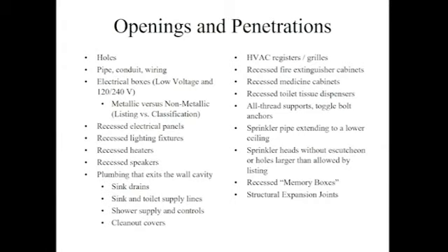Medicine cabinets, I can't say I've seen a rated medicine cabinet yet, so you need to be very careful about how that's detailed. Putting in medicine cabinets or, in Alzheimer's facilities, memory boxes, etc. Recessing them into the wall creates a hole. Toilet tissue dispensers. Oh, people forget about this one. Yes, it's very nice to have that recessed toilet tissue dispenser, so it's not sticking out nearly as far from the wall, but it's a hole.